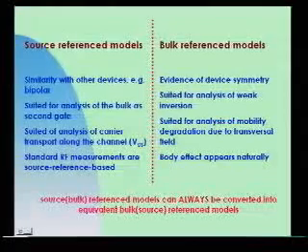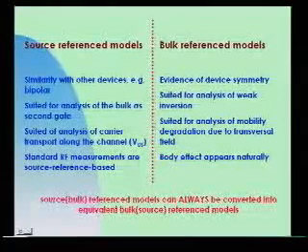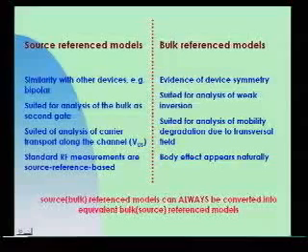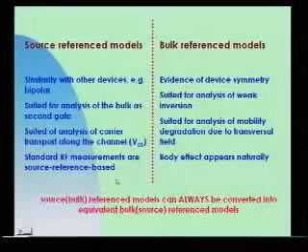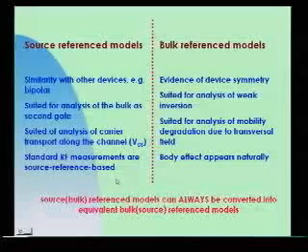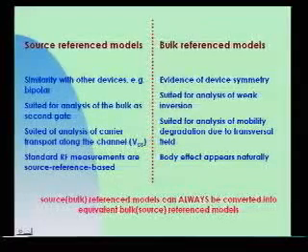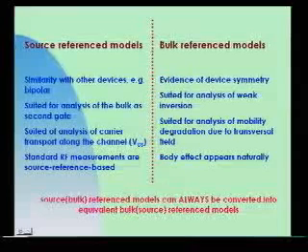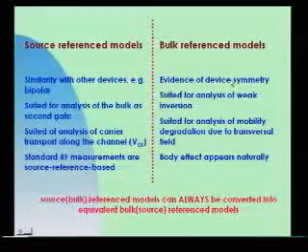Sure, because we are treating the influence of VDB and VSB over the channel in the same way as the influence of VGB. But each model that is source referenced can be converted into a model that is bulk referenced, and also the contrary. So you must not be afraid of the choice you made. You can change it without losing the accuracy of the model you are using. Any questions?